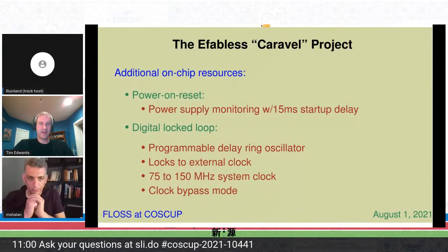The second aspect of the Caravel chip is the user projects and how the users build them. To make sure that the design process is streamlined, the user project designer doesn't and can't modify the design of the surrounding Caravel harness chip. This is necessarily restrictive since it helps to make the whole chip assembly and preparation for tape-out much easier to automate. The user just needs to fill in the area in the middle.